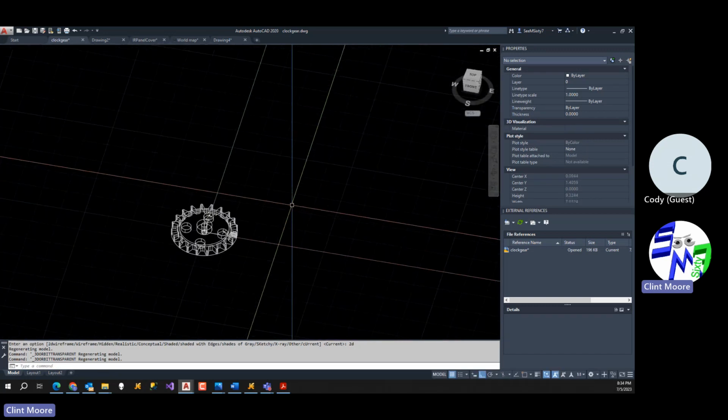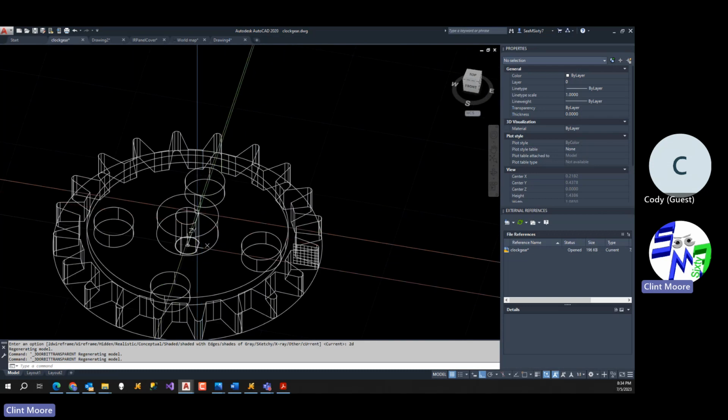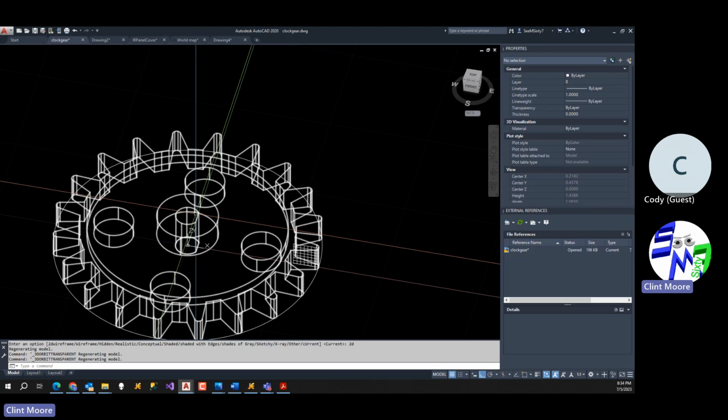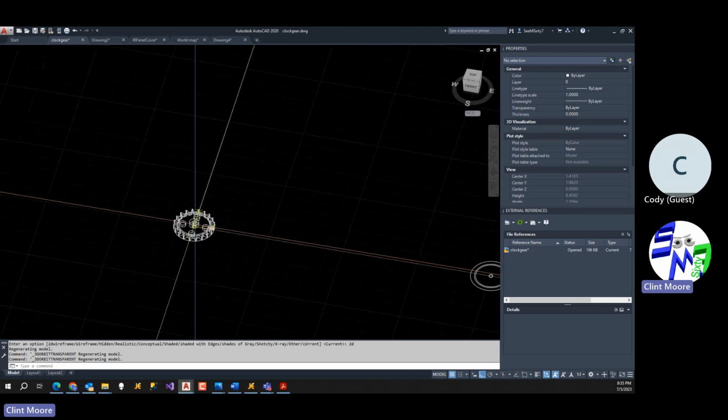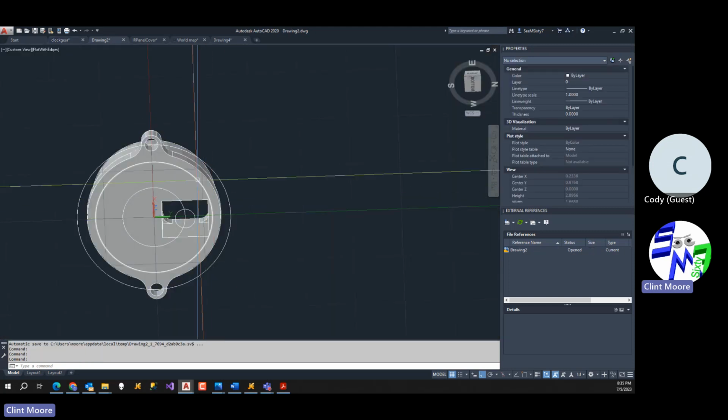So what I had to do here is I had a motor that had a much bigger shaft going through it. And so what I needed to do is make my gear over, but with a smaller, tighter shaft with a small little D shaft in it. So I made that, put that in my clock. That thing works great. Then I also had my motor mount that I had to create.